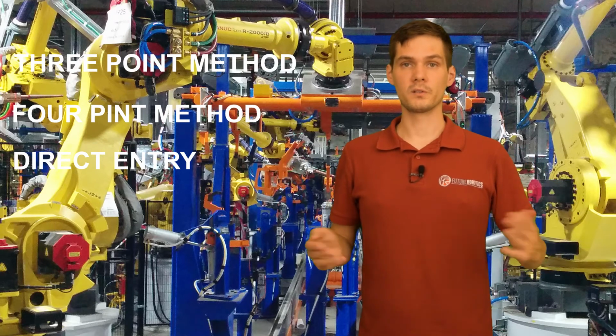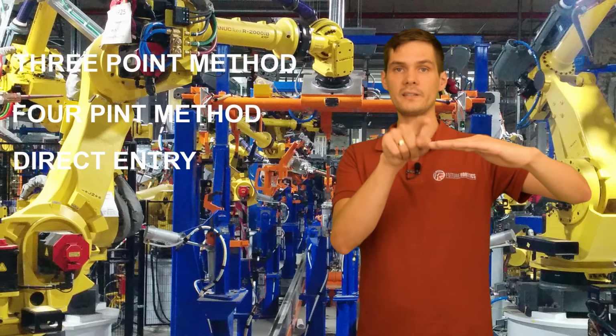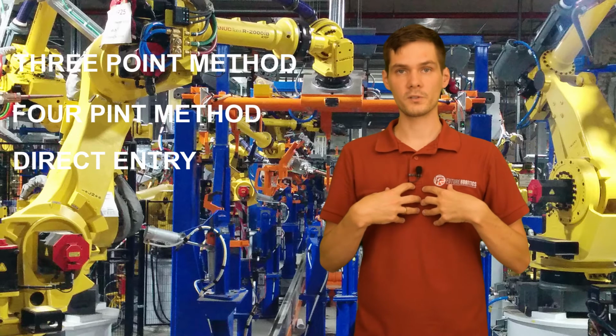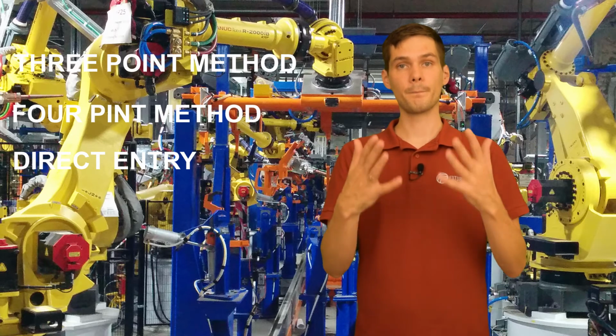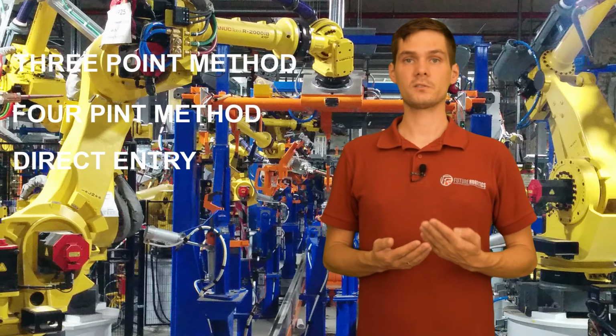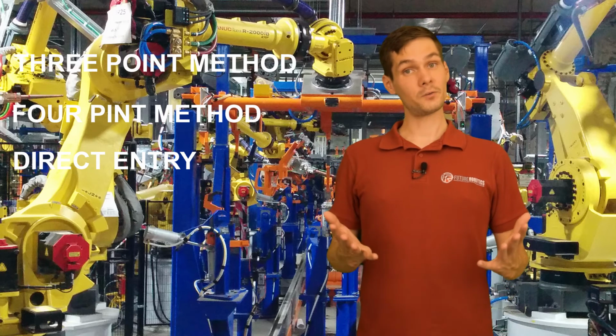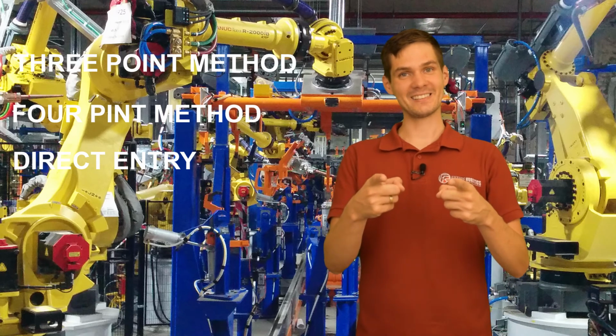So the same for the robot. If you're going to tell him that that's his 0, now he's going to calculate everything from this point, not from the robot base, not from the user frame 0, but the user frame that you taught. And that's why you teach the frames, so it's easier for you to understand the program. So that's it from the theory, guys. Let's get to the exercises.